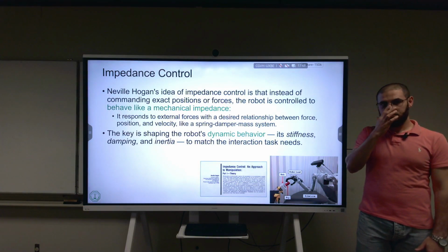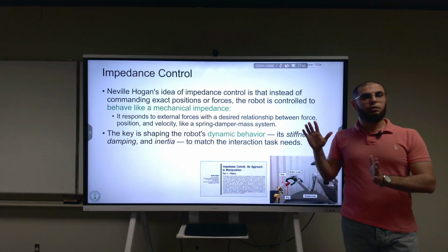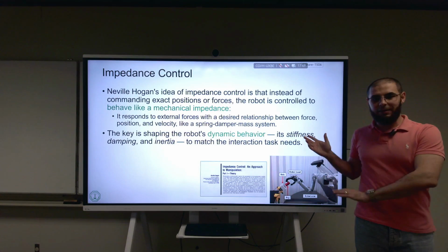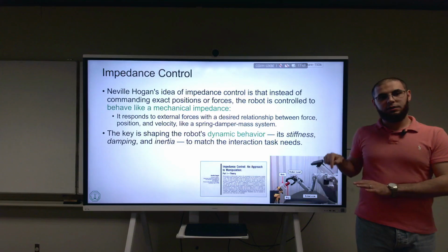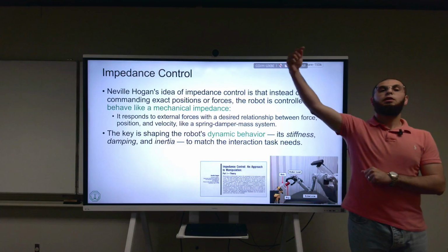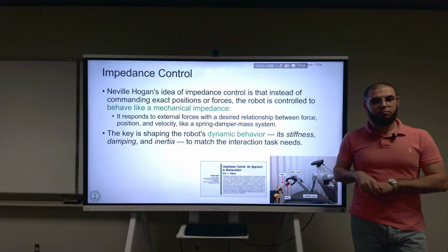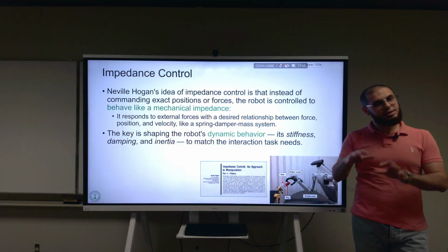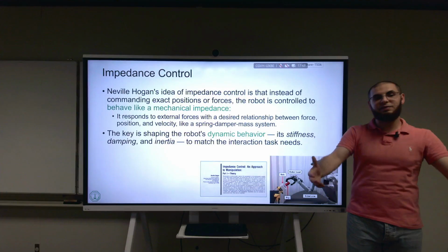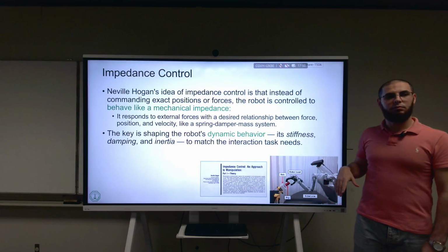For the joints or for just the end effector? The control law for an N-link manipulator is all of the joint torques. We design them thinking about how the end effector will behave. So we replace this system with a mass and a spring or what? We'll do something similar to that. We're going to shape the system so that it behaves as a mass and a spring and a damper. Yes, exactly. That's the whole idea, at the end effector.